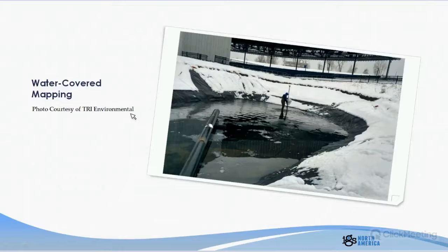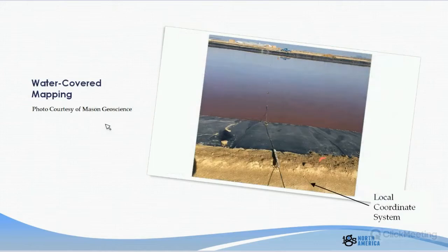I don't perform the beeping-based surveys anymore. I do sometimes the leak pinpoint, but for me, I really like to walk away from a project with a map of exactly what happened so that I can show and document exactly what happened during the survey. So you're still walking back and forth, you're still recording voltage, and it's just connected to GPS, so you can rapidly map it. As soon as you step out of the pond, you can take a look and analyze it for any anomalies that you might not have seen when you're actually walking through the pond. So it's a nice little addition.